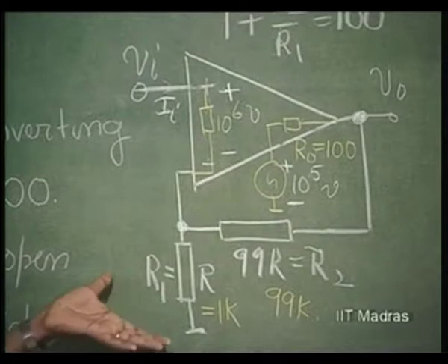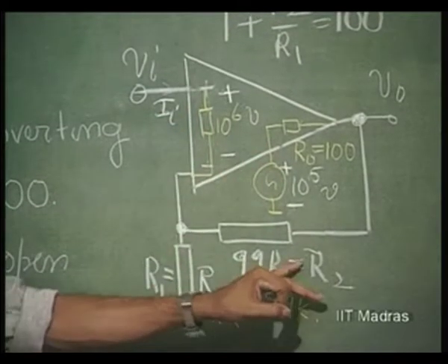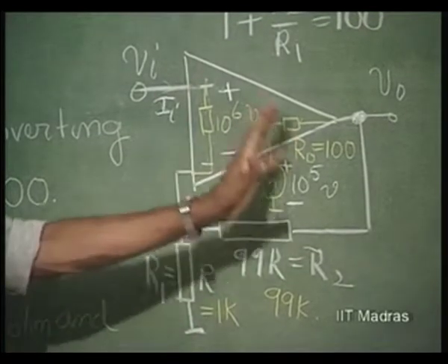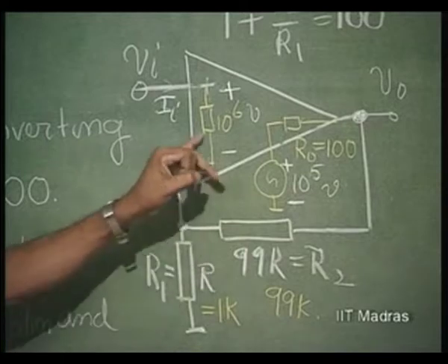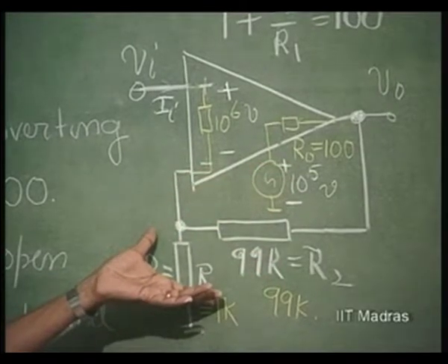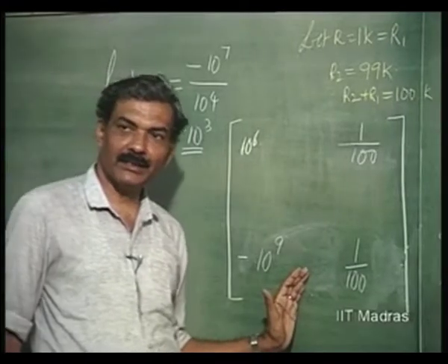So it is very clearly seen here because these resistances are not loading the feedback resistances. Right? So that is why it can be straight away seen that Ri and R0 do not really affect the loop gain much. Whatever is affecting is coming as extra parameter which is negligible. Right?